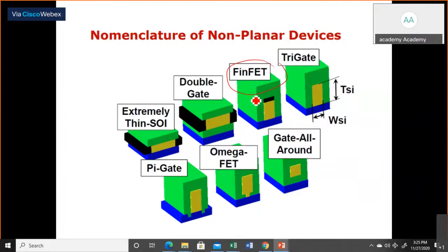Because of the FinFET, you can see here there is a double gate architecture, gate one here and gate two here. Okay. In tri-gate, we have all around gate one, gate two, gate three, and all are connected together. Similarly, different architectures have been proposed in the literature. The most famous architectures are FinFET and tri-gate. Tri-gate, why? Because Intel is working on the tri-gate. And FinFET, like TSMC, I showed the list of companies. TSMC especially works on the FinFET architectures. Okay.